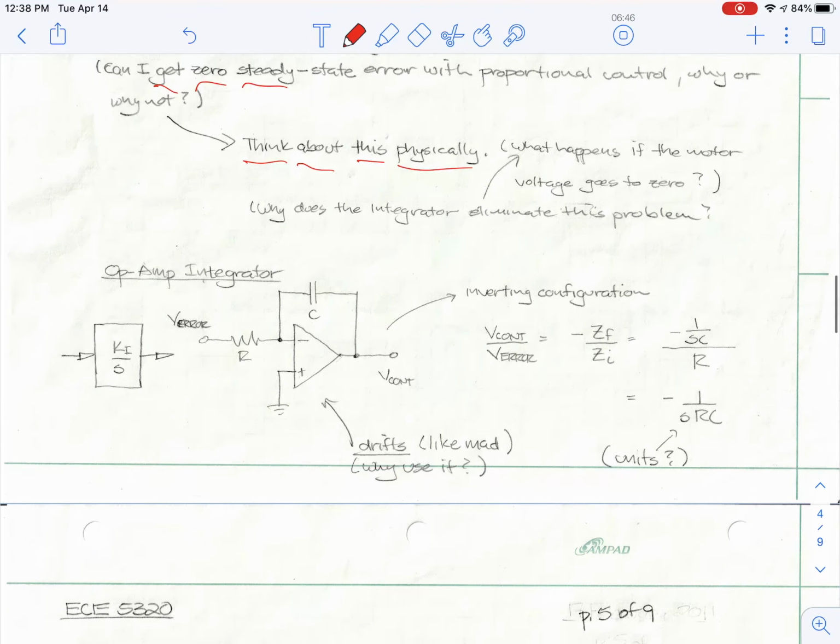Okay, so I can build an integrator simply out of an op-amp. Resistor, capacitor, I do the formula. Go back to op-amps are easy if this is mystifying you. And I get that. What this has is some scale factor and a 1 over S. And it's got a negative sign since it's an inverting configuration. Something, again, I'll have to take into account while I'm building the system.